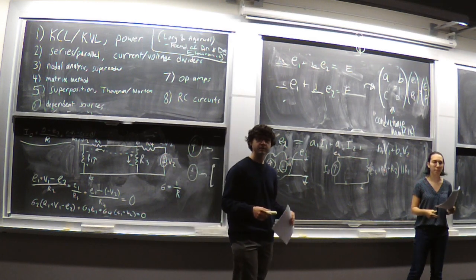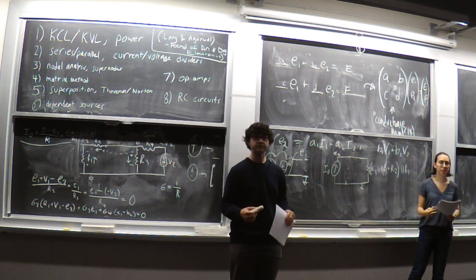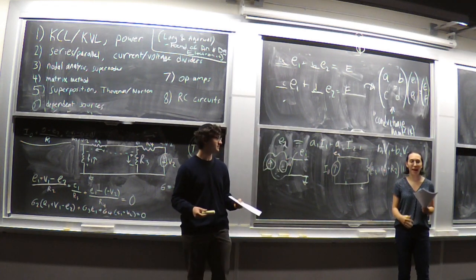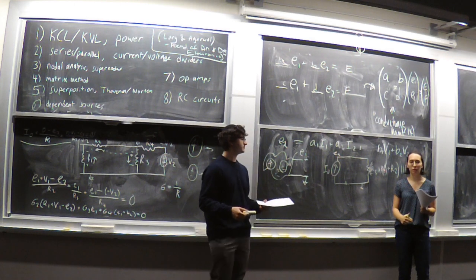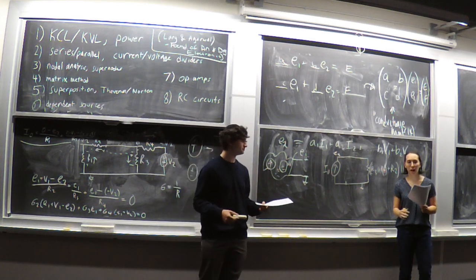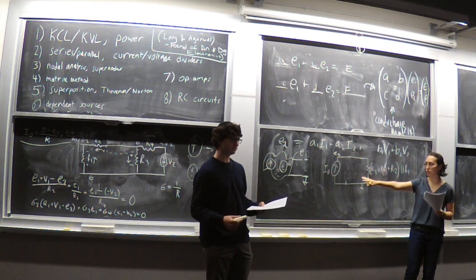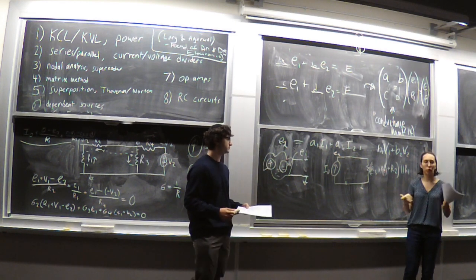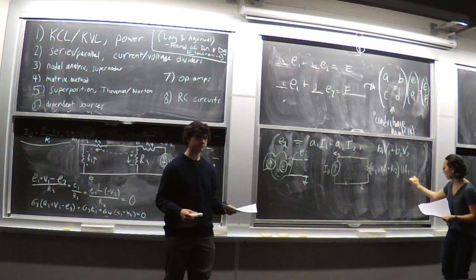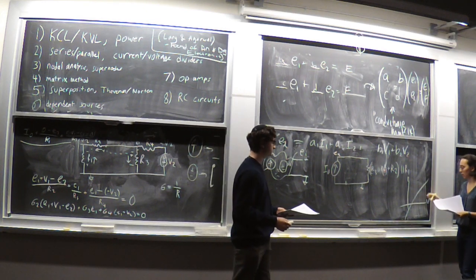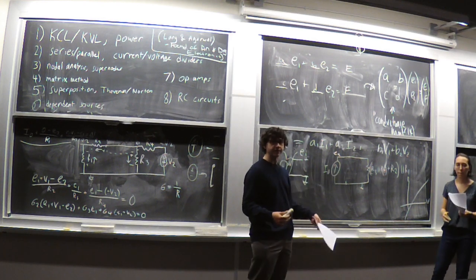Yeah, so an RC circuit at time equals 0 counts as linear. We will get to that after. A capacitor is not really a linear device, and we'll talk about how to deal with circuits involving that. Right now, these are things for which the voltage is proportional to the current, so anything that you can draw on an I versus V plot. If it's a straight line, then it's linear.